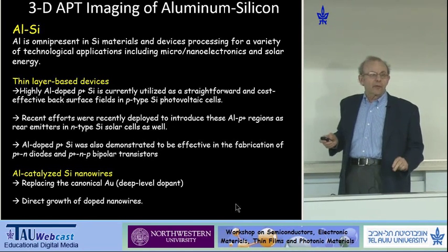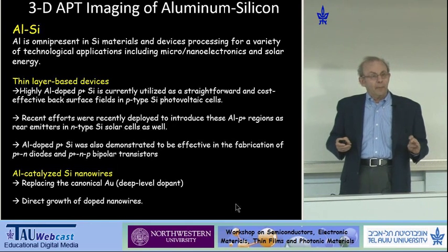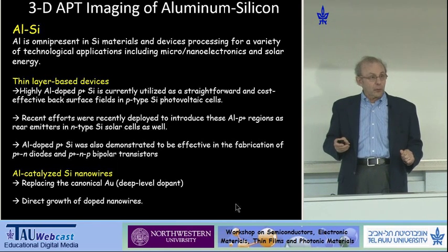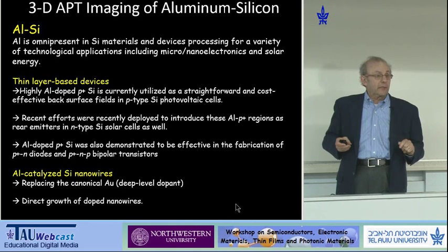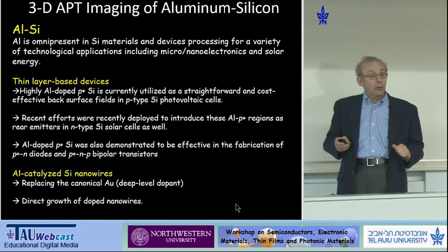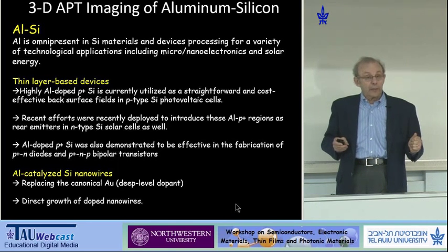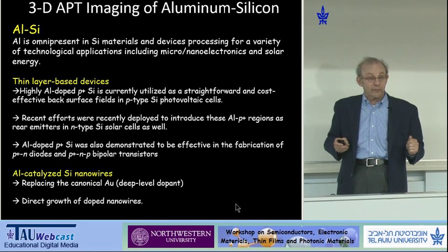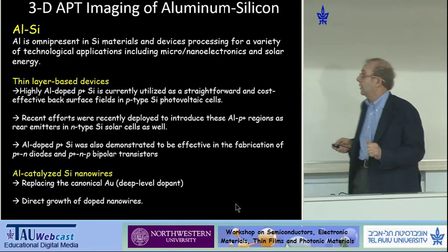When he was at the Max Planck Institute in Halle in Germany, they had developed techniques there for growing nanowires using aluminum as the catalyst rather than gold. Gold's a problem because it kills the minority carrier lifetime. 10 minutes. Okay, I'll just do this.